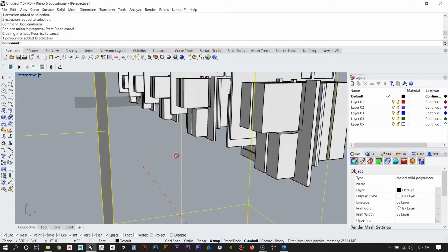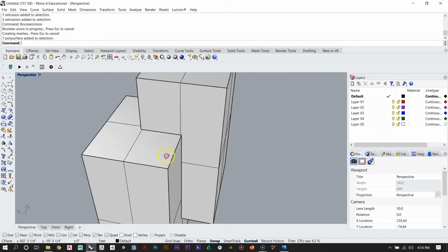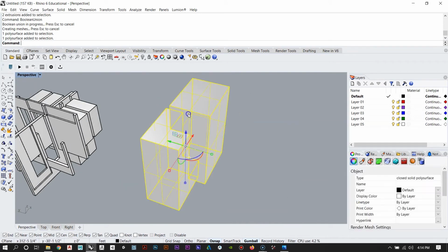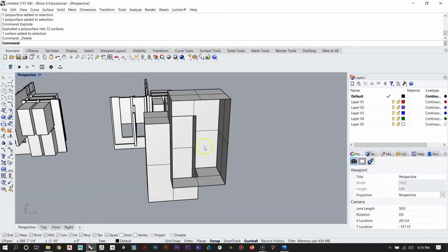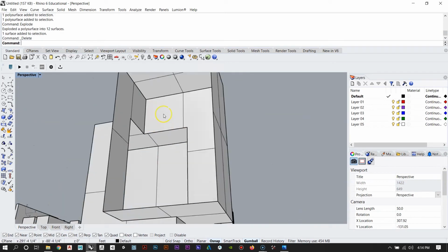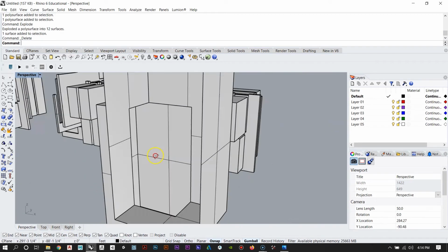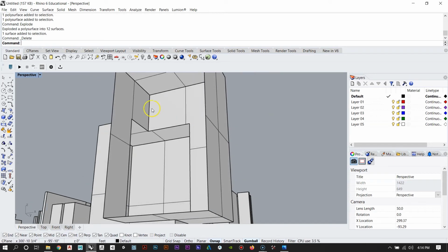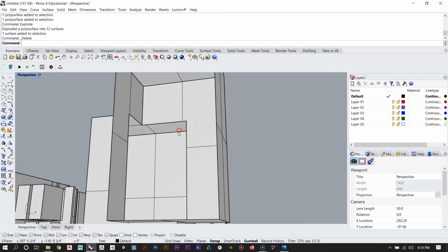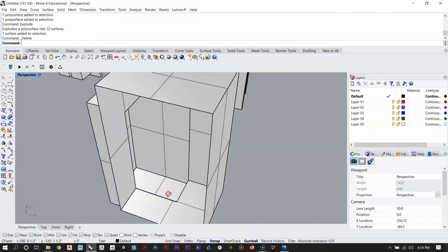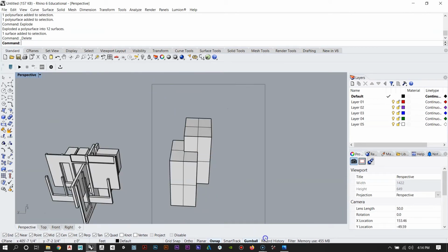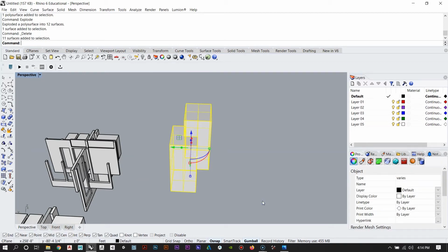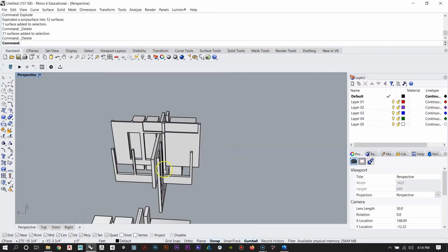So when I zoom inside of them, it's tough to see, but these two objects have been unioned together. Just to show you what it looks like on the inside, I'm going to explode this and delete a face. So you can start to see that it's actually deleted the interior faces and created a single void among the two objects. Okay, so that's the command we're going to use to produce these new columns.